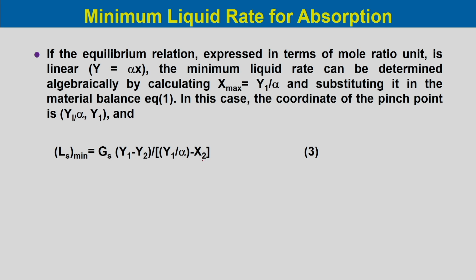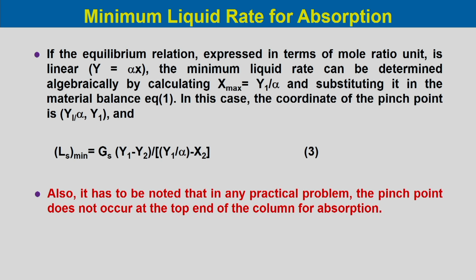Also it has to be noted that in any practical problem, the pinch point does not occur at the top end of the column for absorption. So, the pinch point is observed either at the bottom of the absorption column or at some point inside the absorption column. It does not occur at the top end of the absorption column.